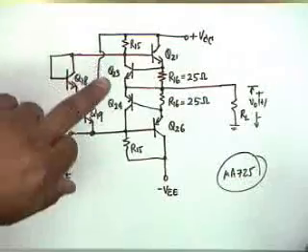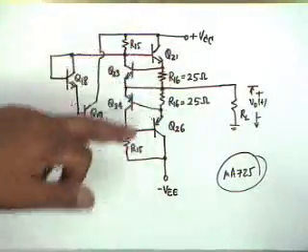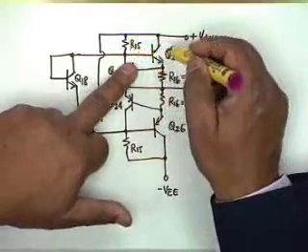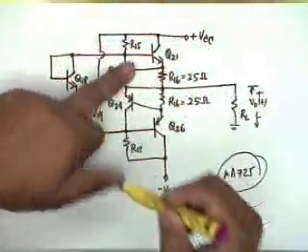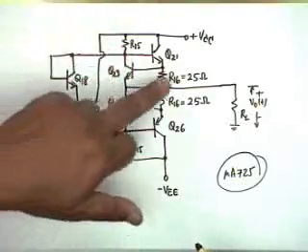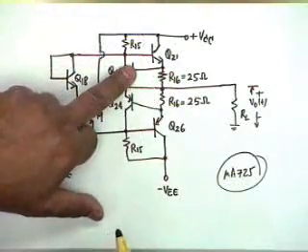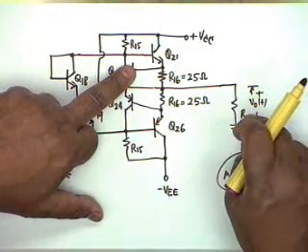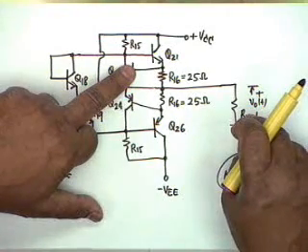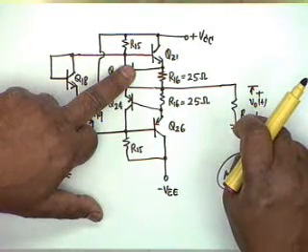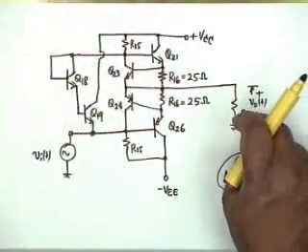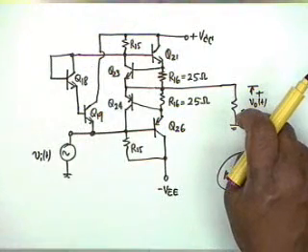Qualitatively, you see, suppose R16 was not there, R16 is 0, and this transistor is not there. R15 is there to be able to drive the base of Q21 and Q18 and Q19. Suppose R16 and Q23 are not there. Then if RL is accidentally short circuited, if RL is very low, then what is the drop across Q21 collector to emitter? It is VCC plus 15, whatever voltage it is.